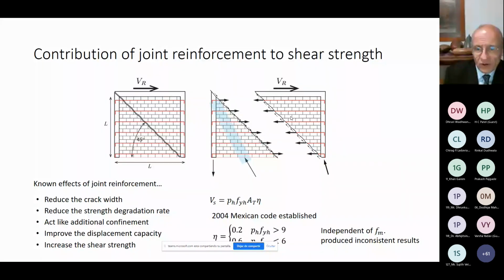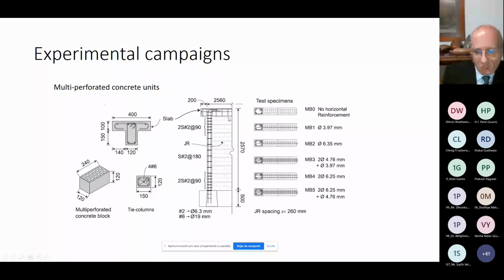And so we tried to figure out what was going on and did very precise experiments to show it. The idea was very simple. We just produced many walls, say 6 walls, with different amounts of reinforcement. The first one didn't have any, and then increasing values of reinforcement. The spacing of the reinforcement was constant in all the walls, so in some cases there was a lot of reinforcement in each layer of reinforcement.